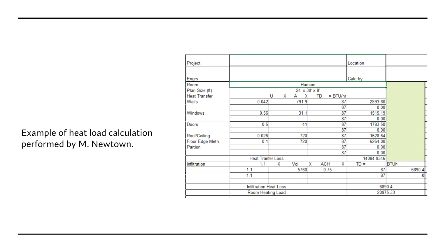And I don't mean to gross anybody out, so hopefully you didn't eat your last meal just recently. But why do you want to breathe air that has walked its way through your outside siding, your insulation, places where the mice have probably run over the last 50 years, in through the sheetrock, past the paint, into the space through your carpet, and into your breathing environment? It's better to have a tight wall and have less air infiltration and then bring in intentional fresh air so that you're able to breathe clean, fresh air.